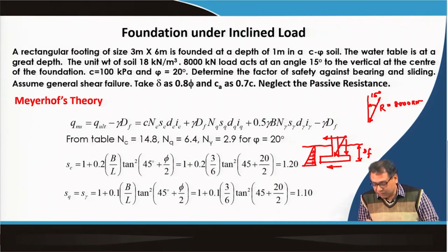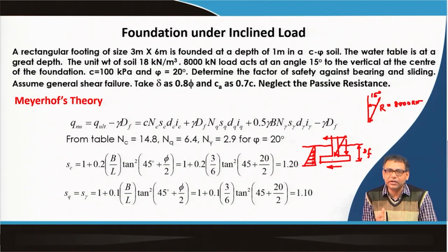So, soil, from where will I get the resistance? I will get this passive resistance as well as resistance from the base soil, because your foundation is sliding. In our retaining wall design and this type of foundation design, we generally neglect passive resistance, because if my foundation is safe without considering the passive resistance, then obviously it will be over safe if I consider it.